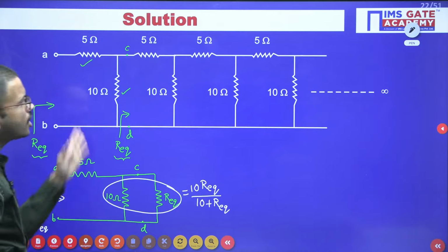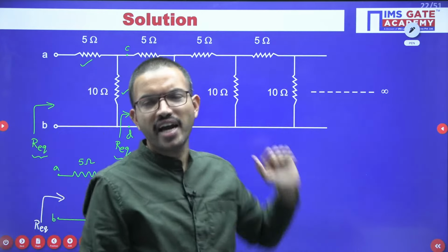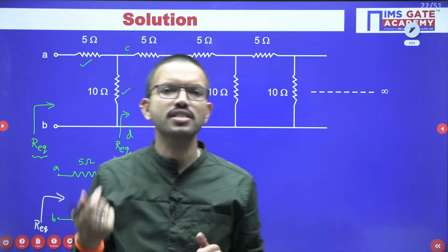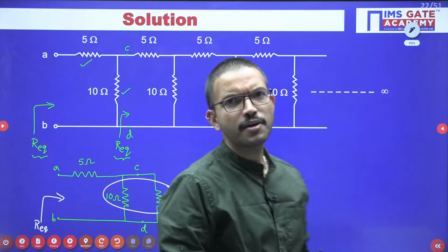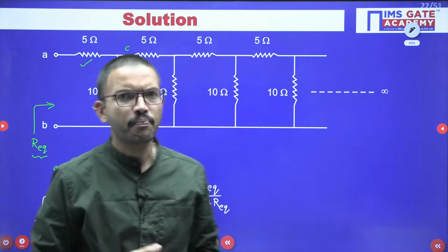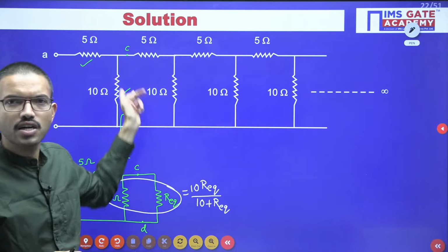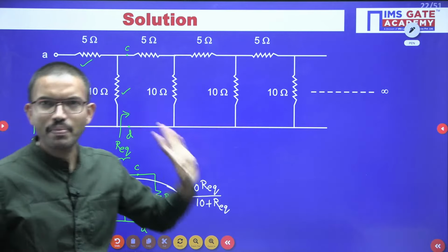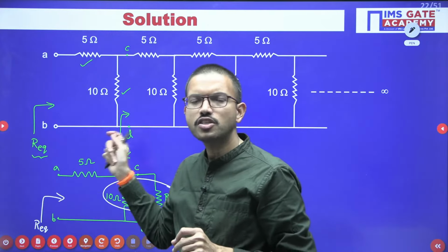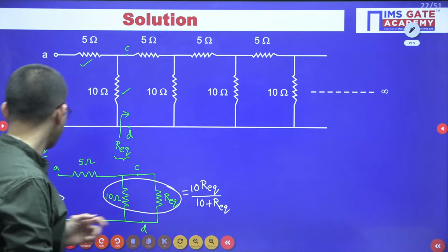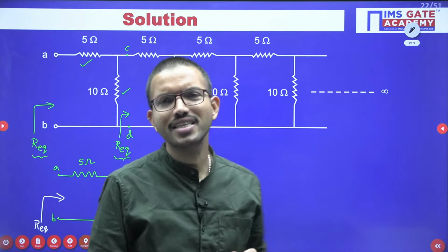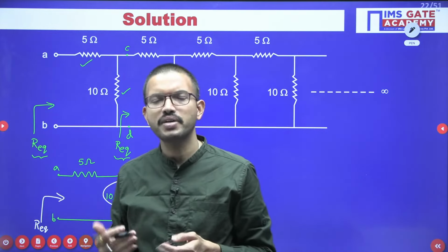Because in this network, if you observe, all are resistors only. And in fact, in general, we will represent resistor value positive unless otherwise source. Okay, sources when you are studying transistor or FET, etc. Because those are sources, they will be having negative resistance. But here all are passive elements, right? So whenever you are having passive elements, after calculating the equivalent resistance, obviously you will get positive resistor value. So that is the reason. Whenever you are having some dependent source, etc., that time if you are solving any question regarding the equivalent resistance, sometime you can get negative because it is a source.